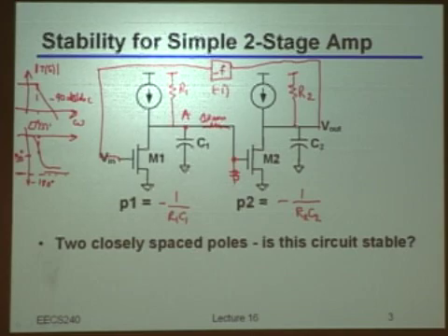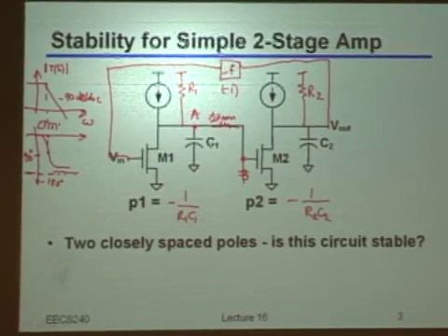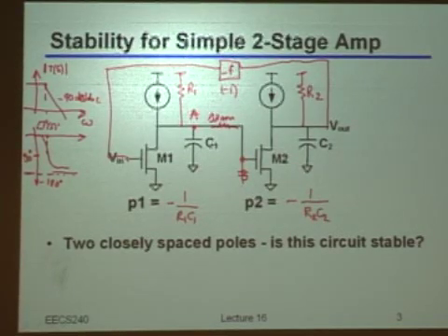And even if it was stable, could I just be happy about that? It might happen with a very small phase margin that my settling behavior would not be the one that I desire. So, for instance, assume that you have a very small phase margin and you have a step. What kind of behavior would you expect for the amplifier with a small phase margin? So it doesn't oscillate, most probably, because mathematically we still have a good phase margin. It doesn't oscillate, but it settles very slowly.